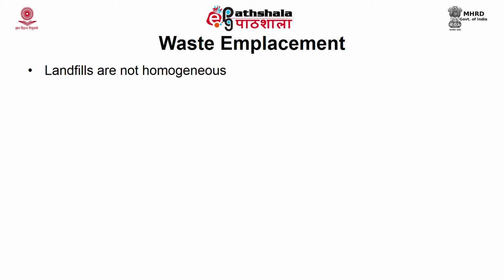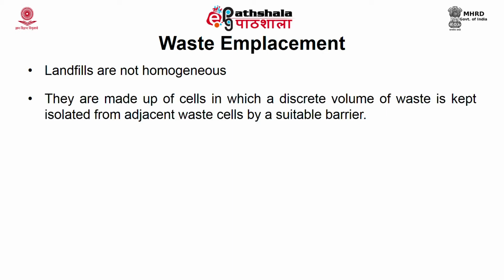Now, landfills are not homogeneous and they are usually made up of cells in which a specific or discrete volume of waste is dumped, and these cells will be isolated from the adjacent waste cells by a suitable barrier. Now, there are 4 methods followed for waste emplacement or waste loading. The first one is the trench method, area method, cell method and canyon or depression method.